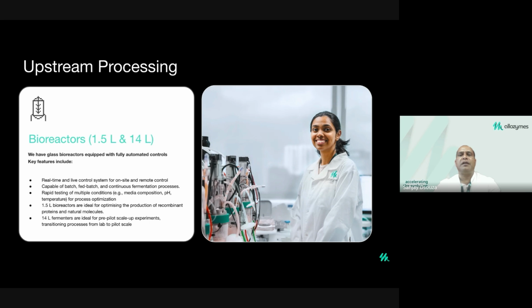And these are all fully automatic. We can monitor and control the fermenters in real time. These fermenters can also be run in batch mode, fed batch mode, and continuous mode. The 1 liter fermenters help with rapid testing of media, pH, and temperatures. At higher scale, that is 14 liter, we call it the pre-pilot scale, where we optimize all the parameters before we move on to a bigger one, that is 100 liter.